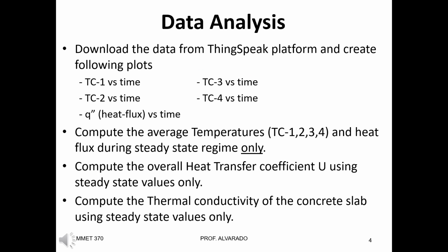As I mentioned before, during this experiment we're going to measure all the temperatures from TC1 to TC4, and we're also measuring the heat flux with respect to time. This data will help us to measure the heat transfer coefficient, that is U, and the thermal conductivity K of the concrete slab in the steady state regime.